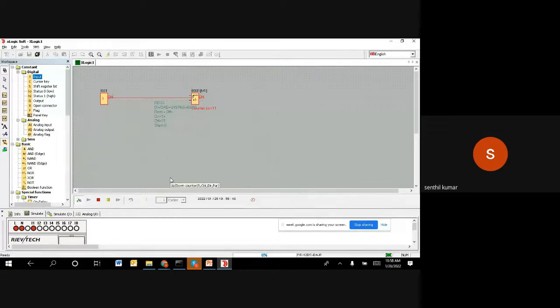Now, if I keep toggling this bottle production, once the 15th bottle comes, you can see the output go off. So I'm going to do it now. Off, 11, 12, 13, 14. So 14 produced. Now if I make it 15, we should see the output going off. Now the count has become 15, and you can see the output has gone off.